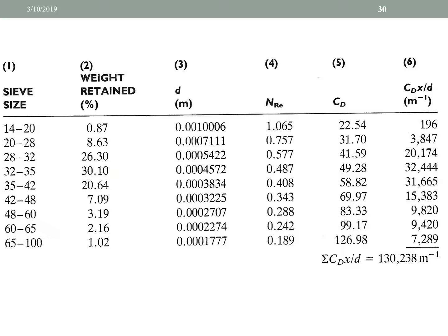Exactly here the same. That is the sand of the filter. You take it and do sieve analysis, and then you measure the weight retained. Again, based on all of the classes, when we talk about weight, we mean mass. It is not right to say weight. All of these numbers are mass of sand, so you can correct it. That is the mass retained.